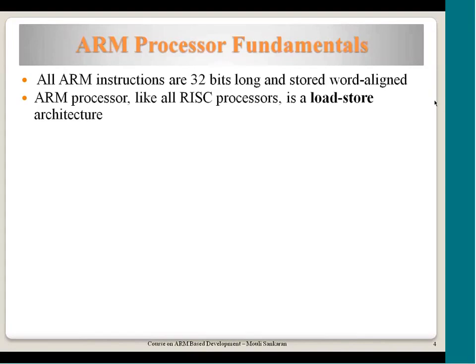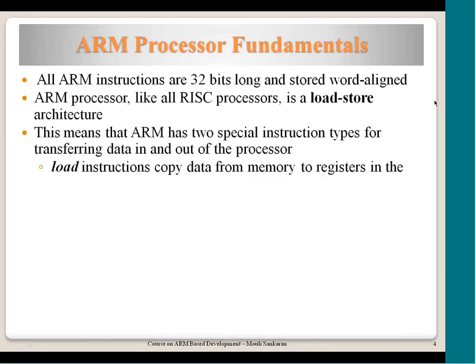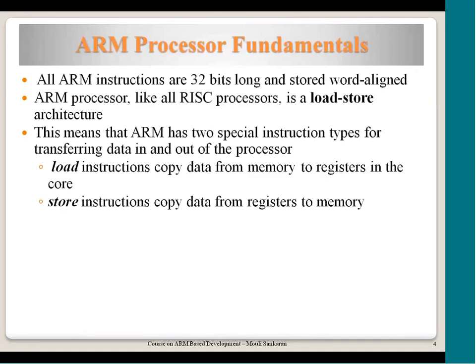And as you are aware, this is a RISC processor with a load store architecture. That means anything to do with memory is done using load or store instructions. That is, if the processor wants to read a particular data from memory, it has to use a load instruction, and if it wants to save any value in the register to memory, it has to use store instructions.